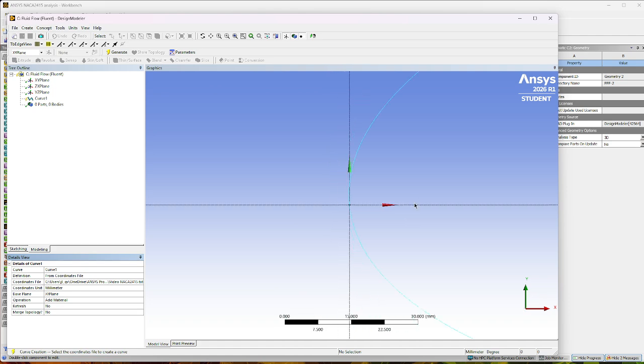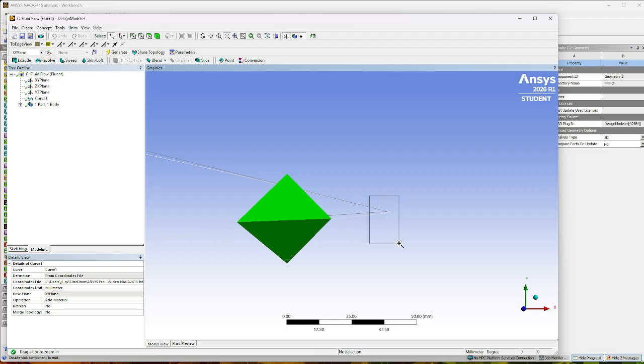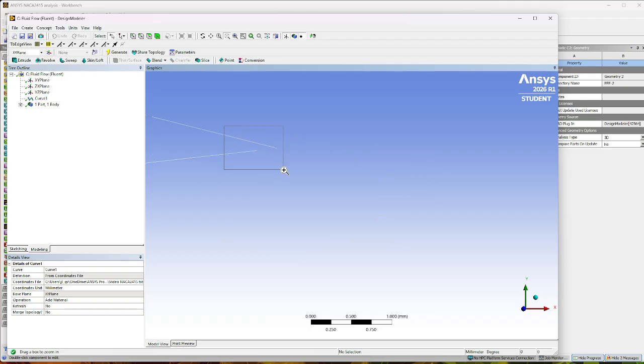Like that. And so we're gonna click on top here, generate. So it generates this. But a warning though, let's rotate this a little bit. If you go here, you zoom in to the trailing edge here. Since we deleted that last point, this is not going to close and it's not going to create the surface that you need.